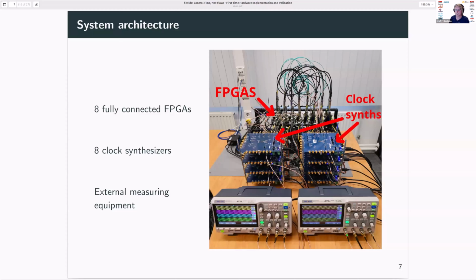And for our experiments, we set the step size of these frequency changes to 10 parts per billion. That means that for every billion clock cycles ticked, the clock synthesizer will add 10 extra and then smear it out over that whole period. And to give you an idea of how mind-bogglingly precise these boards can be, these boards that are fairly cheap support step sizes as low as 1 part per trillion, which is way overkill for our application.